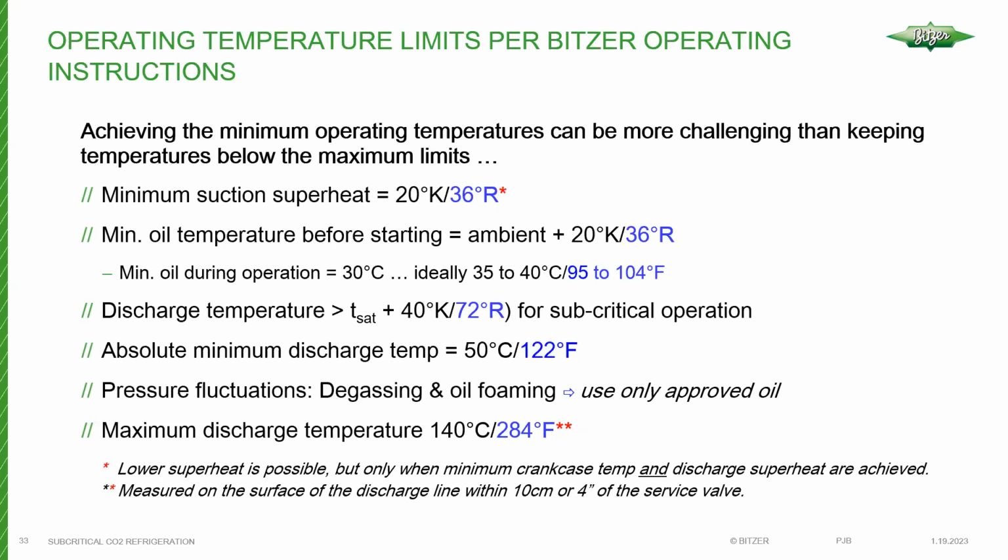But we never want to make the assumption that we've been doing this for many years with HFC systems. So I know what superheat is, I'll set the superheat on the CO2 system the same way. It's very much different because, like I said, the solubility of CO2 and POE are higher, more chance of strong degassing, which leads to oil foaming, which is never great at lubricating a compressor.